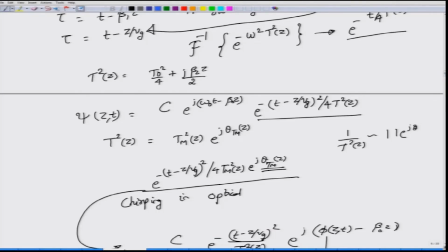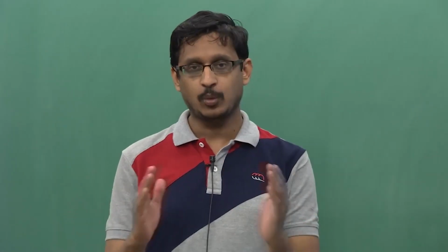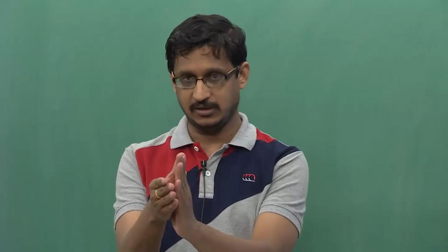We said that dispersion is a very important topic in optical fiber, and that is clearly so because it causes pulses to spread out, and once pulses start to spread, then the rate at which you can send the pulses is limited. You send in one pulse, you have to wait until the pulse has spread properly, because if you send in a pulse before the pulse spreading has been taken into account, then the pulse as it propagates would spread and then it would actually invade into the other pulse's territory. So, it essentially starts to talk to the other pulses, giving rise to what is called intersymbol interference. So, pulse spreading gives rise to intersymbol interference.